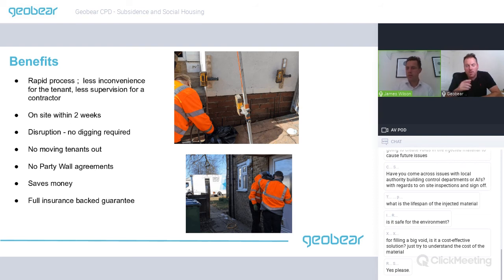Yeah, James, just to add to that point, we've got a secondary product, GORT, which is a real-time displacement control solution. It's essentially compensation grouting, where we've designed packers now, where, like James says, there's an issue with the expansion, but we can actually inject those at real depths, and that's something we're working on in the background. It really wouldn't be applicable to residential properties. This is for tunnel boring situations, but that is one for the future as well.